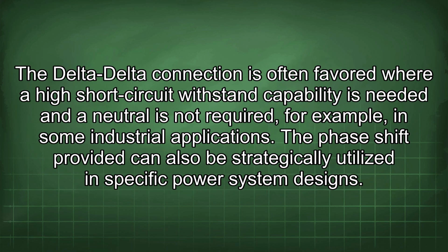The delta-delta connection is often favored where a high short-circuit withstand capability is needed and a neutral is not required, for example, in some industrial applications. The phase shift provided can also be strategically utilized in specific power system designs.